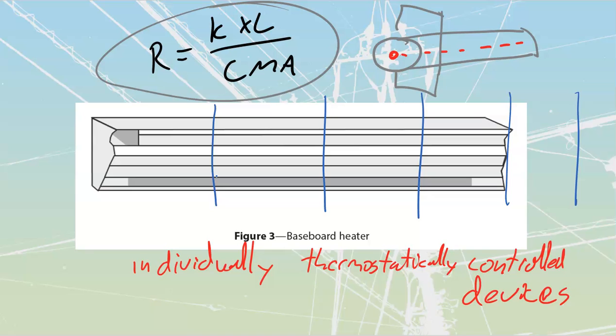Voltages for these ones are generally higher is better, because we know that watts are equal to my I times my E. So if I go to a higher value of voltage for the same amount of watts, I go to a lower value of current, and then we can get away with smaller conductors that are going to be run out to each one of these components.